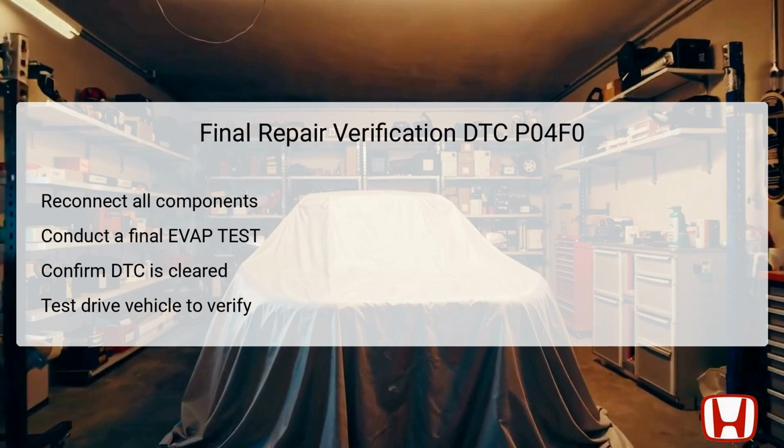Once you verify that the DTC has been cleared, a test drive of the vehicle is warranted to confirm that all systems are functioning as intended under normal driving conditions. Monitoring the check engine light during the test drive will help validate the repair's success. Ensure that there are no persistent symptoms and that the vehicle runs smoothly.